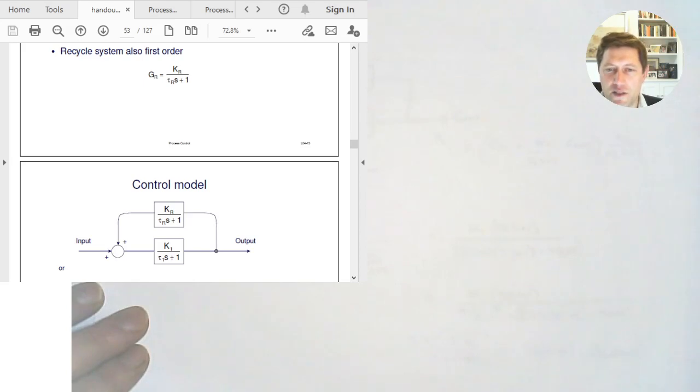Each of these has a transfer function, and due to the linearity of Laplace transforms, we can simply add the two things together here to get a function for what's coming out of it. So the objective is to create the transfer function for the overall system, given the individual components and its schematic.